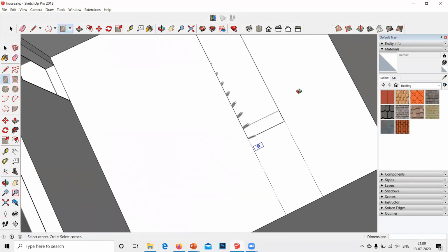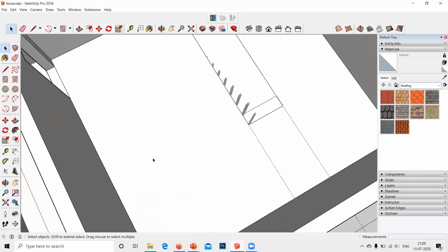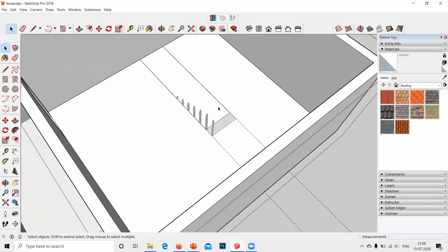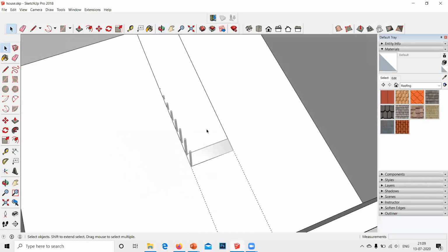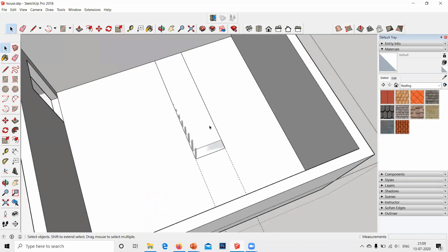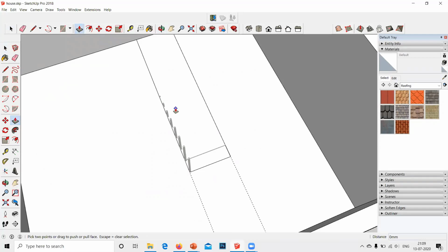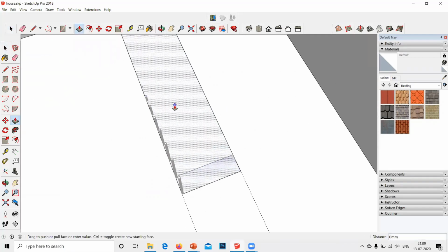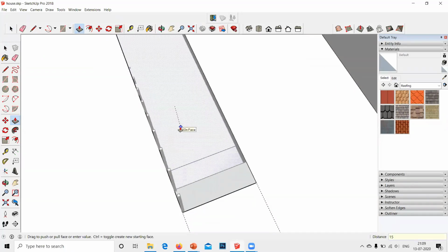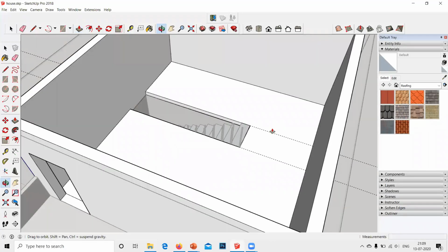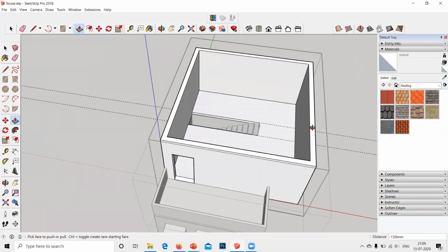See, as I already told you, while making a slab, it is 150 mm thick. That means there are 2 layers. Okay, I just undid it to tell you this thing. There are 2 layers. Instead of deleting it, you can simply do what we do for pushing and pulling. Use this push and pull option and go inside and enter 150. See, we have created it.